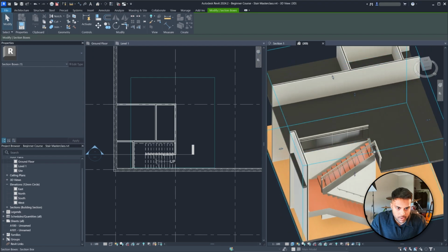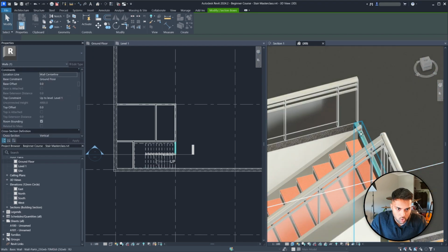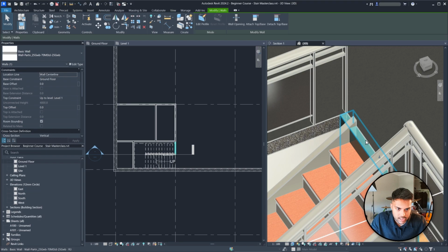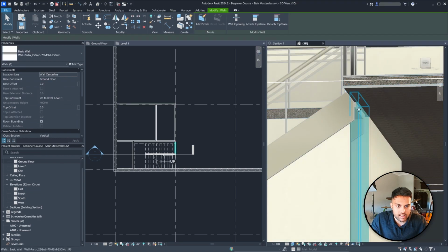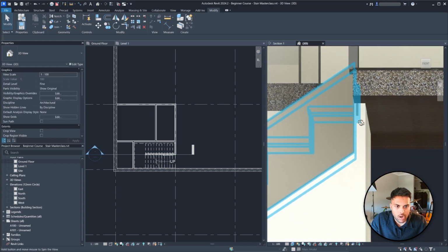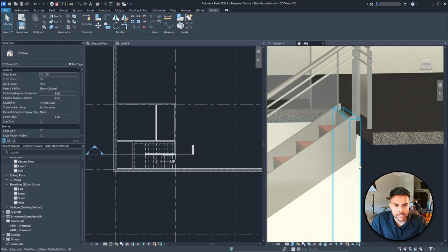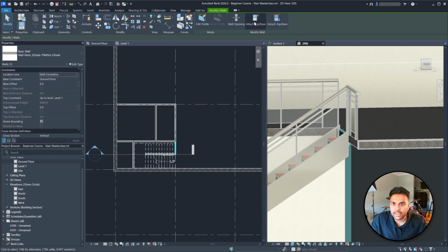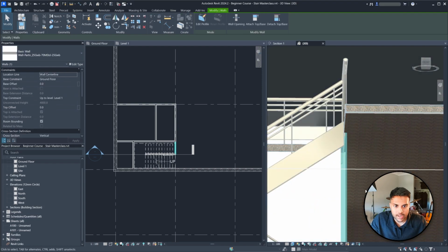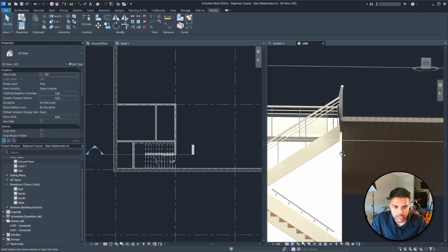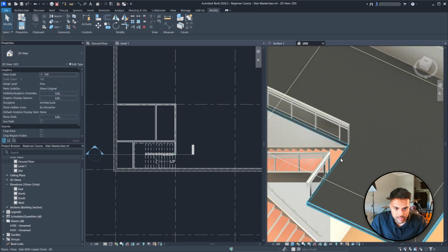One additional thing is, you might see there's an issue with this wall extending all the way up to the top of that slab. I just noticed that. So what we can do is edit this so that it sits underneath the slab. So we'll have to click that wall and attach to the top base. We'll have to click that, and that should do it, right? So we no longer see anything protruding out.